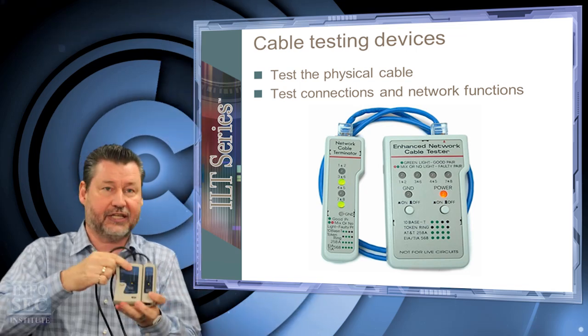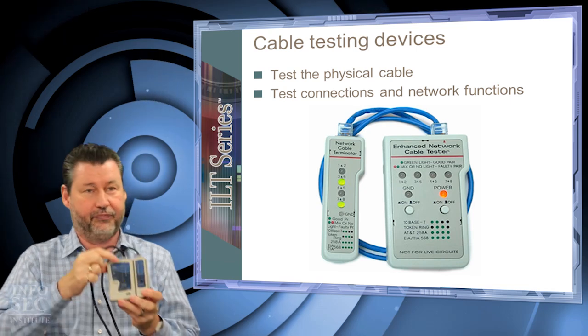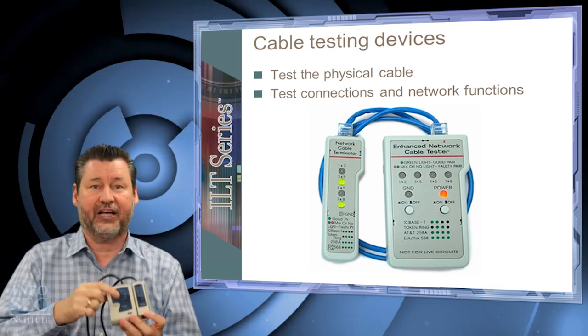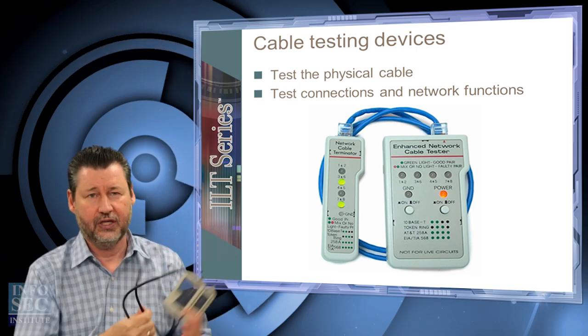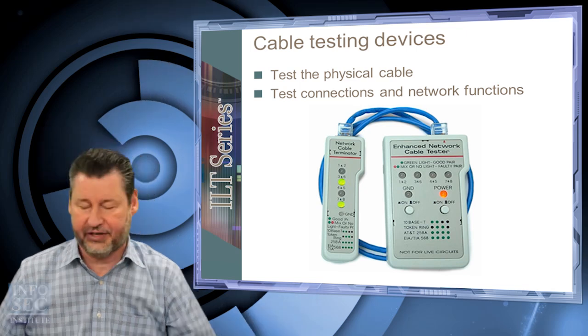Okay, it counts down, goes down saying they're all good. Let me put it in slow mode. So it's checking each one. You'll notice they're the same because this is a good cable. You can check functionality of that cable, make sure it works, not miswired.